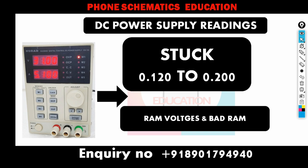Also, sometimes the RAM is attached combined with the MMC circuit. Nowadays, in some phones, the RAM is given separately by the companies. So if you see this type of reading, you can work on the RAM, the complete RAM circuit, the voltage requirements, the enables. Also, if it is a separate RAM or a double decker, change the RAM.